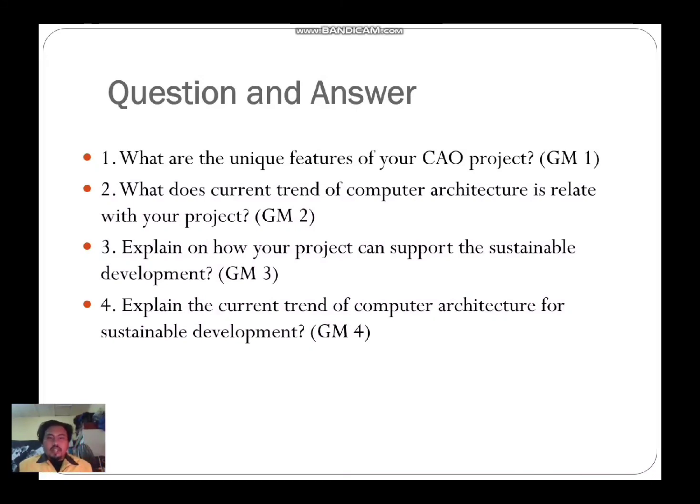DMA is a subsystem that can move data from one place to another autonomously without intervention from the processor. For example, if you have a 512 byte sector on a hard disk that has to be moved into memory, then you prime the DMA system by giving the memory address to move the data to and the number of bytes. Then you wait for the disk to rotate to the beginning of the sector. And the data is read from the beginning of the sector, and as the data is read, it is picked up by DMA and moved 1, 2, or 4 bytes at a time to the specified memory address.